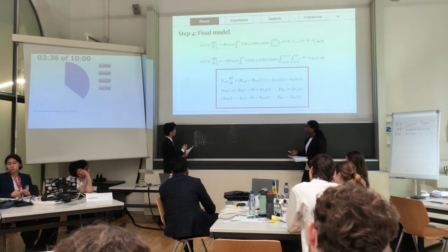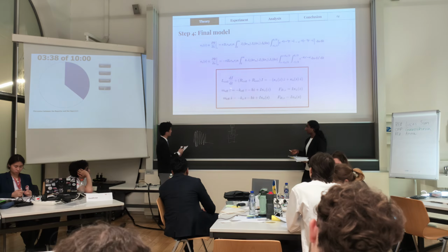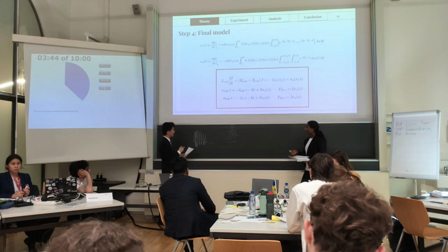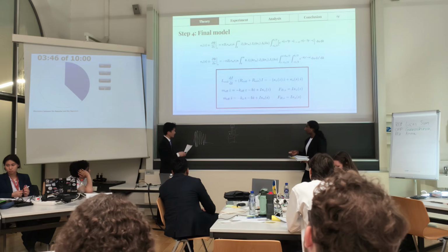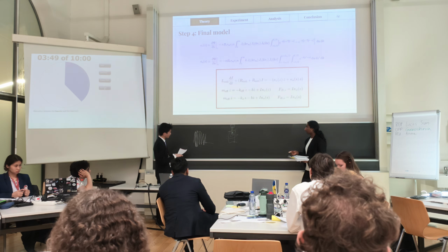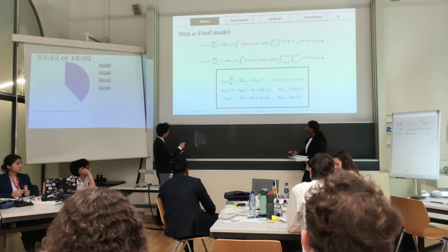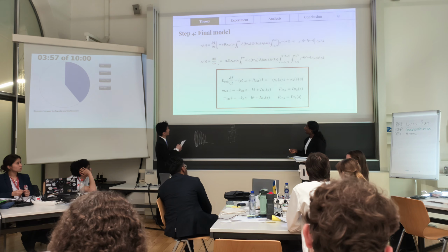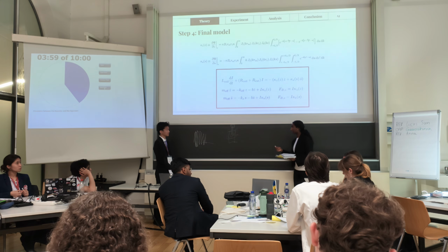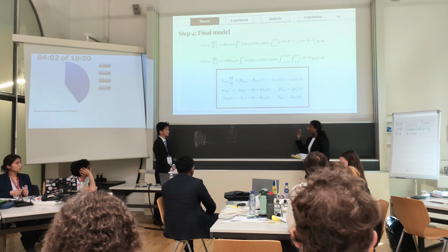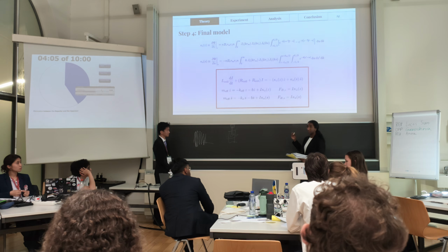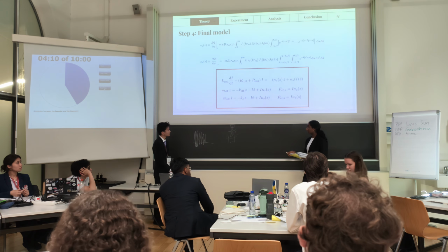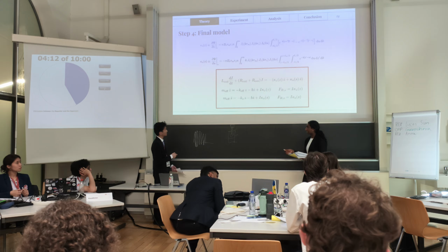The reason the inductance is not important is that the angular frequency of oscillation is quite small, with a spring constant of around 8 units total. When we increase the spring constant, the natural frequency will increase, and when the natural frequency increases, this derivative over here will increase, and so that will make this term more significant. So if I understand correctly, your opinion is that the inductance is governed mainly by the mechanical motion rather than electrical effects? Just briefly, yes or no?